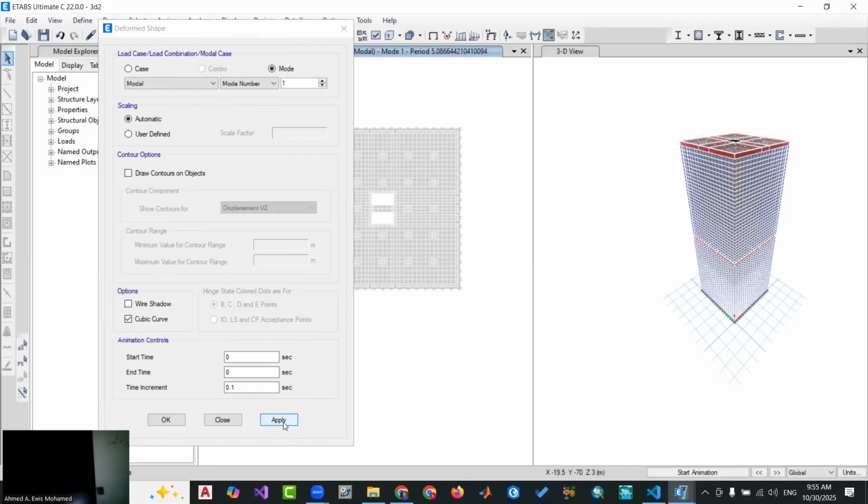For example, this one, which we can name as a cantilever mode shape because it's like a cantilever, takes a lot of mass going in this side. For this other mode shape, it can happen too, but only a small part of the building goes this side, while a lot of the mass of the building goes in this mode shape.